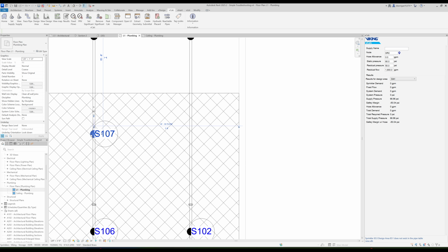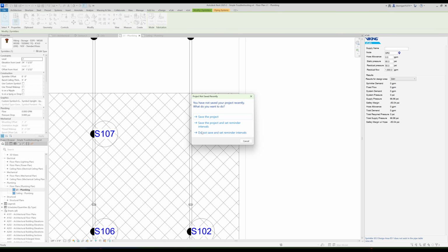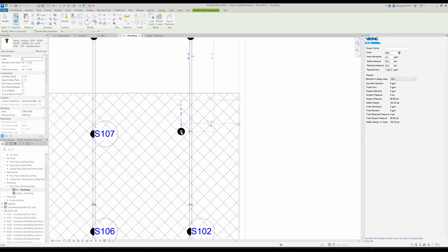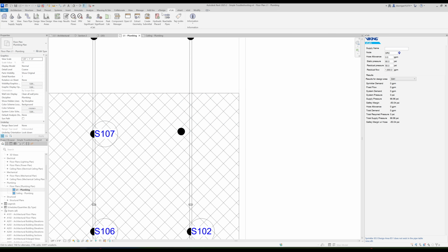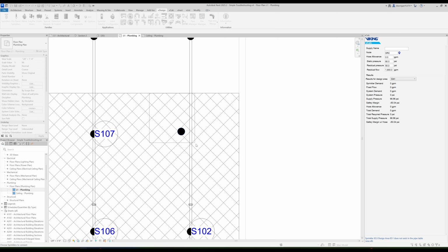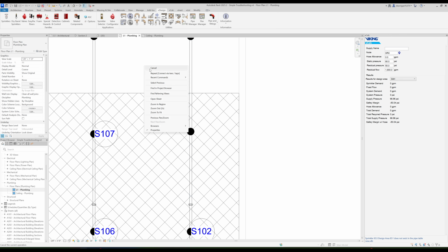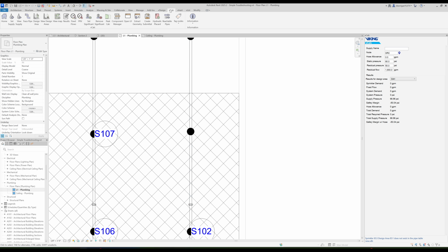Even if I were to run a create similar, drop one over here, and then connect it up, so I'll just go to vDesign, connect it in. It's not perfectly in line, but that's fine. But even in this situation, when I run trace pipe, you'll see that I still have the same error because that problematic sprinkler still exists in the design area.